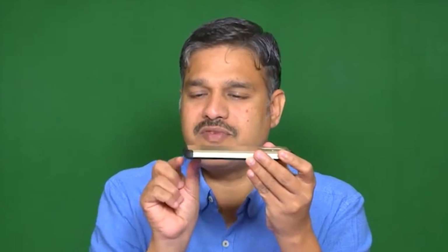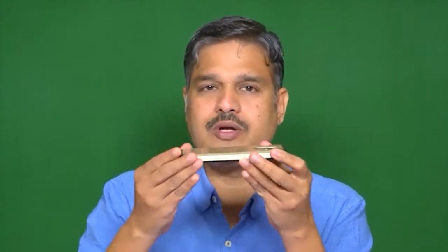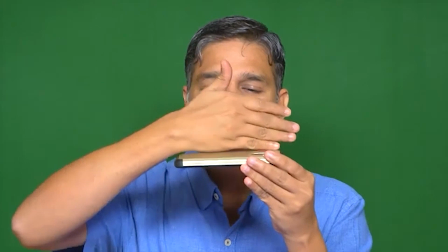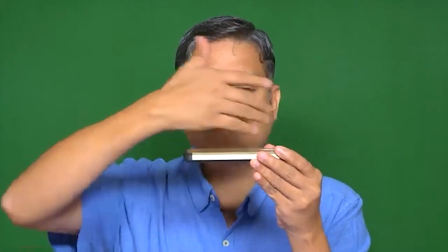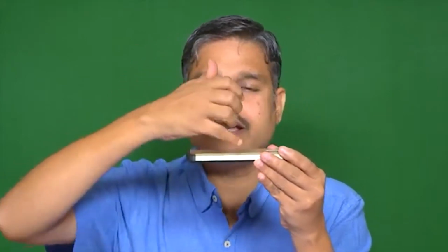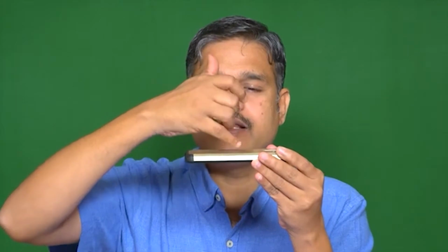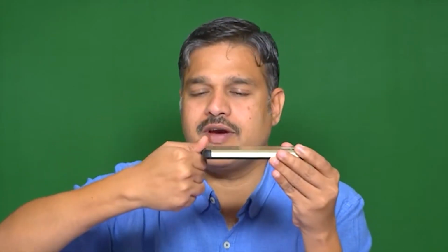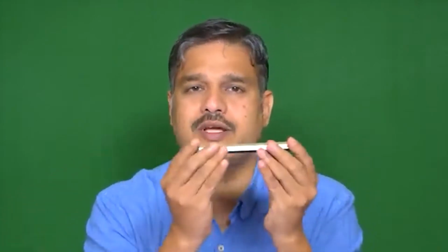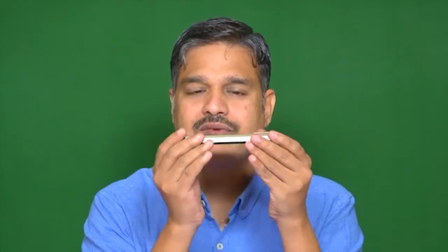If the stiffness of all the supporting columns is the same on this side and on this side, and the center is exactly in the middle, then the intersection of the diagonals is both the center of mass and the center of stiffness. If both lie on the same point and I pull, it will translate in one direction only, with no rotation, and similarly in the y direction also no rotation takes place.